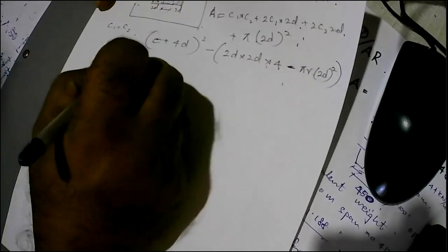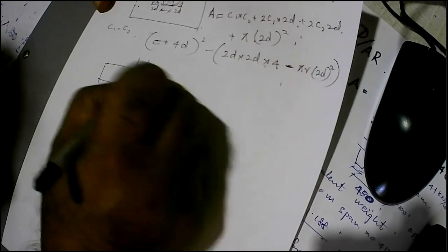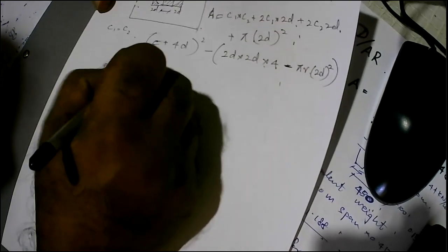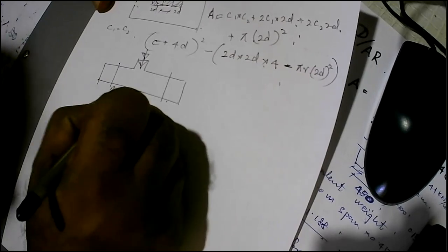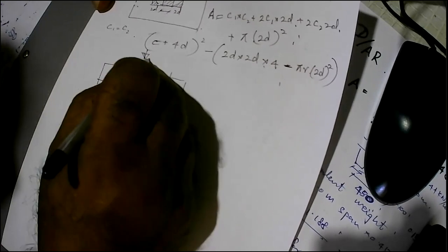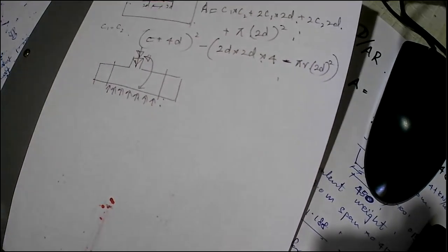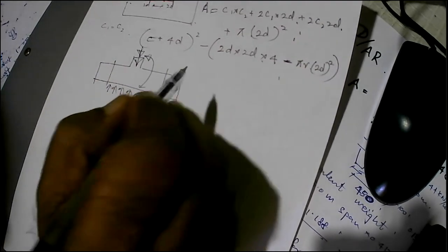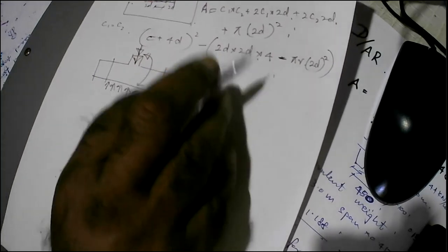Then the important thing is, when you look at this base, the punching shear perimeter is somewhere here. So there's a load acting downwards and there's a load acting upwards. So the punching shear will be caused by the difference of these two. So there's a force downwards and also a force upwards, and this is a substantial force.